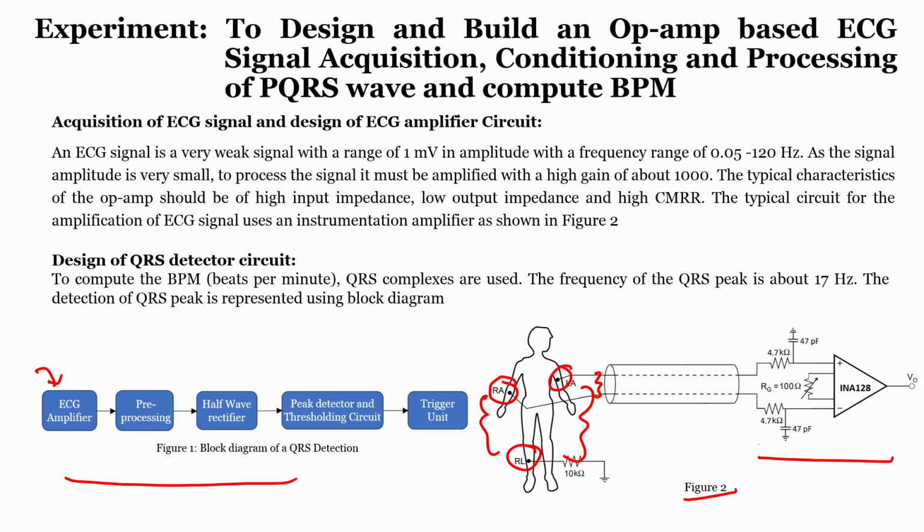And moreover, when we observe the amplitude of the ECG signal, the maximum amplitude is within a range of 1 millivolt, and those are really small amplitudes. Moreover, it will always have very low signal to noise ratios, right.